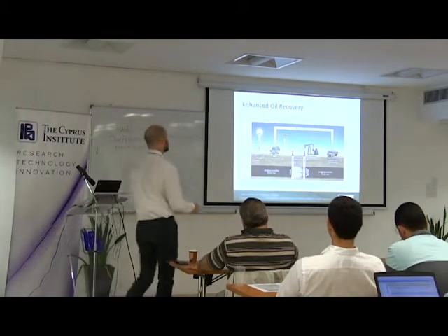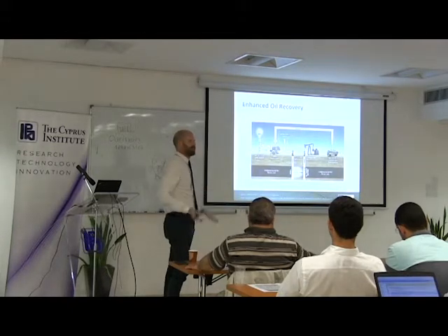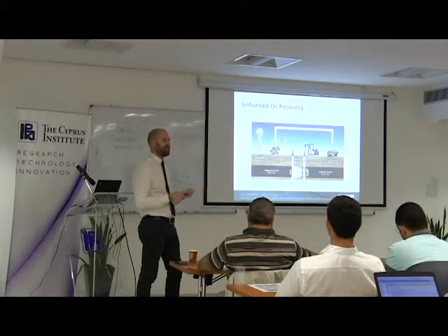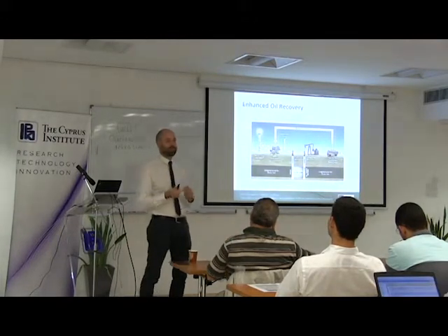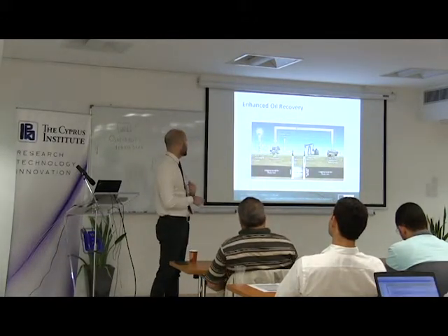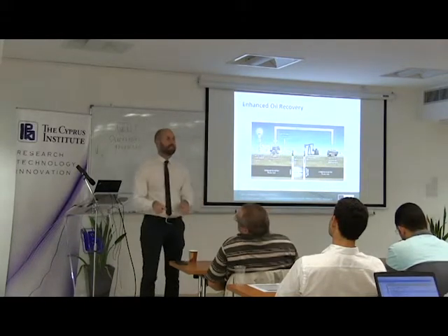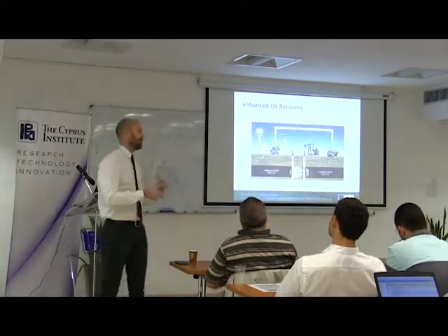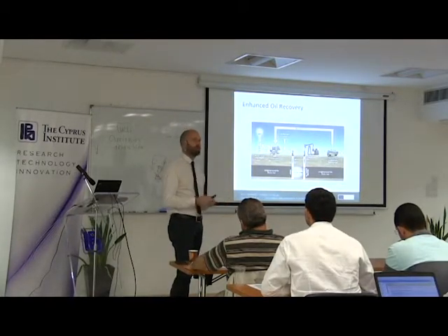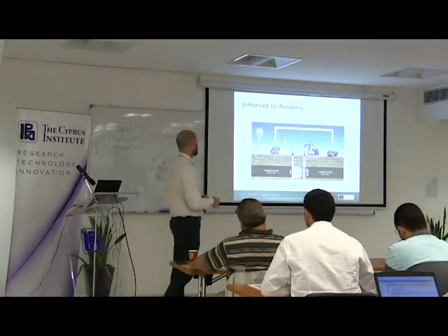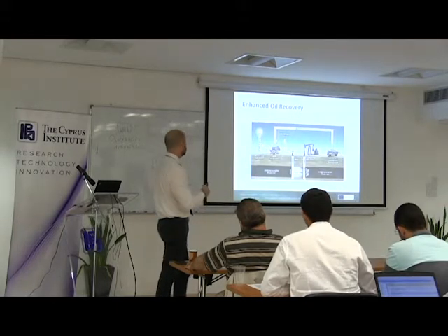In this case, it's not only a problem of pressure to bring the oil out, it's also a problem of viscosity of the heavy oils contained inside the porous rocks. So the injection of steam inside the injection wells ensures a better flow and the possibility of exploiting also more difficult fields.